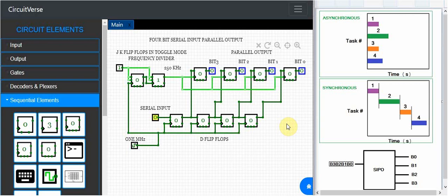Basically, we should be able to, for instance, put in the 4-bit number 1111 and, as a serial input, create a parallel output. So for instance, if I change the input here, and let's say right at this point I put in 111, you're going to see that it does create a parallel output of 1111, and that input could be 1010, it could be 1110, whatever that 4-bit input is going to be, it's outputted